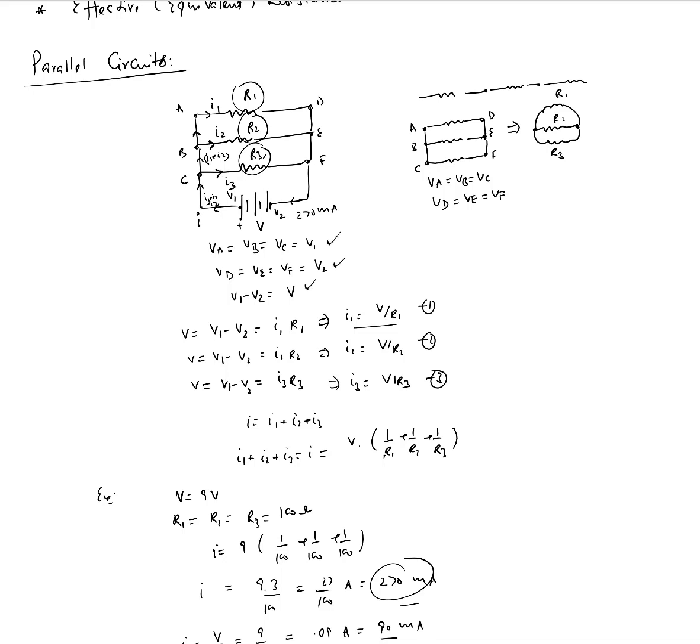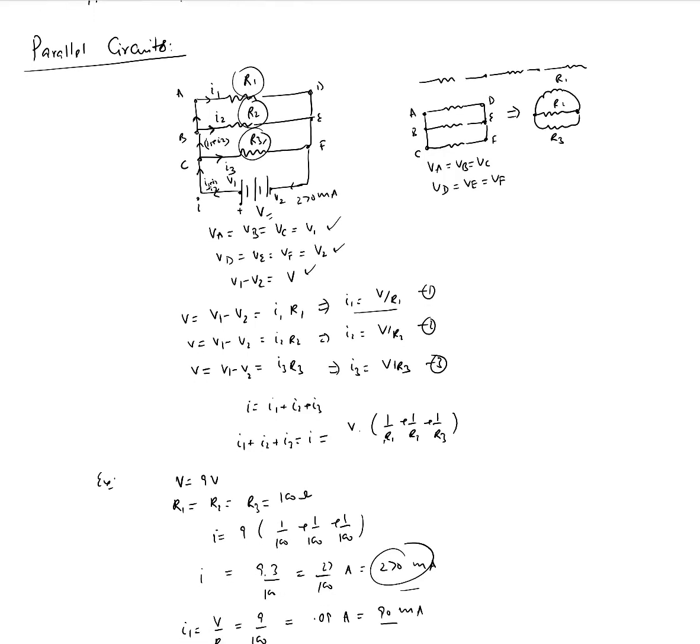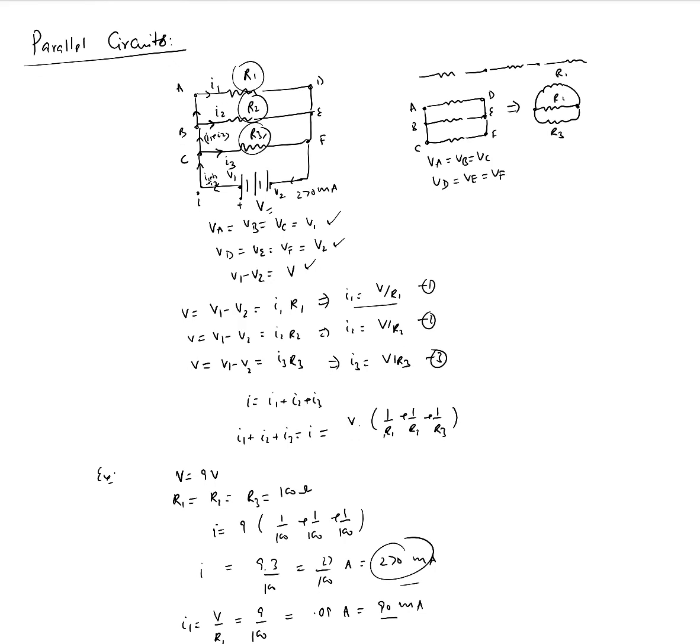We said that the voltage drop across each of these three resistors is the same as the voltage drop across the battery source. Okay, now the last question to answer is, what is the effective resistance for this circuit? So effective resistance as seen by the source of this circuit, which is the battery, right? So if I have to replace this with one single circuit where I have my battery intact, that's 9 volts, and then I want to replace all the resistors that are here in parallel with one resistor of effective resistance, what would that be?